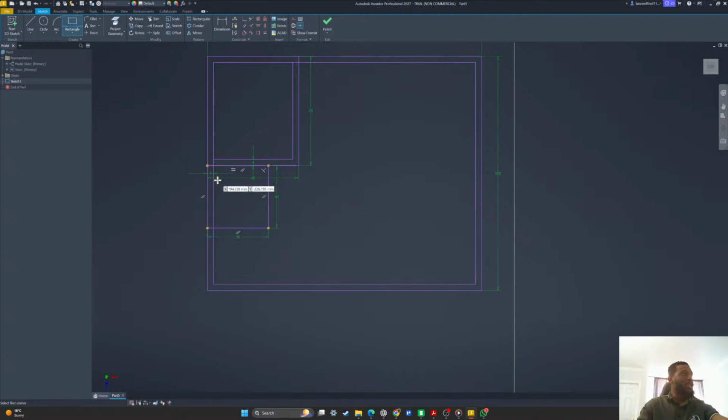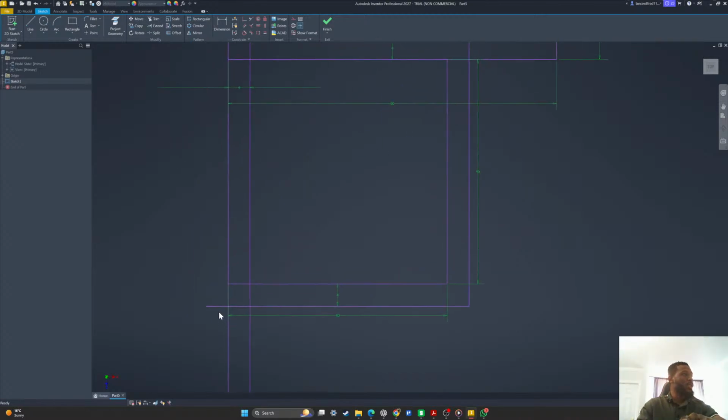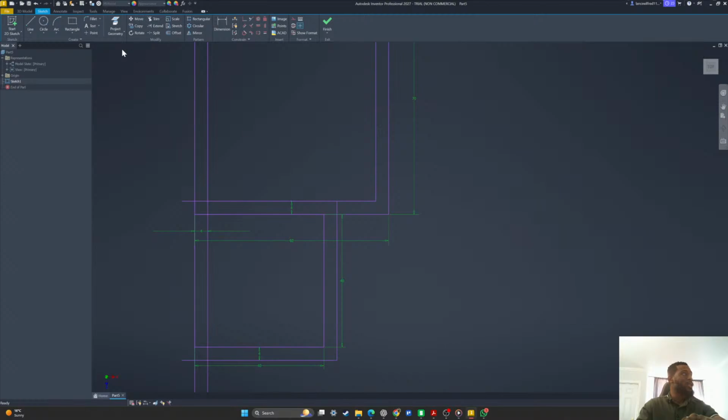If you remember in the last class, I told you that you have to make sure that all your dimensions are accurate. You cannot do this halfway. You must make sure that everything is complete and precise, or otherwise your print is going to fail. So I want to extrude this outward 4 mm, because if we take it inside, it's going to be too big. And what we can do is delete these extra lines that we don't use.